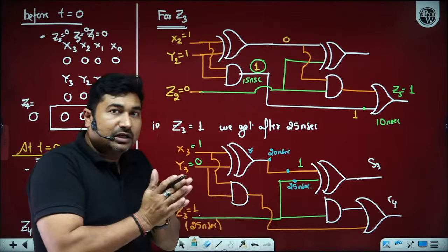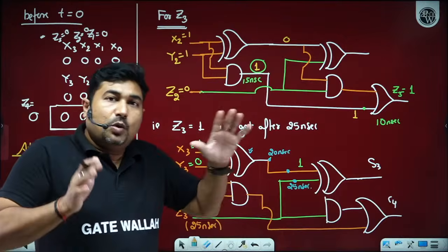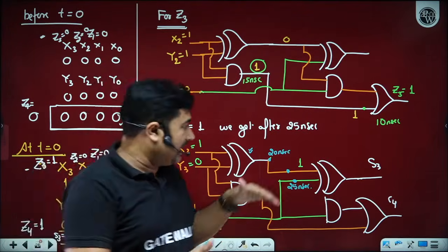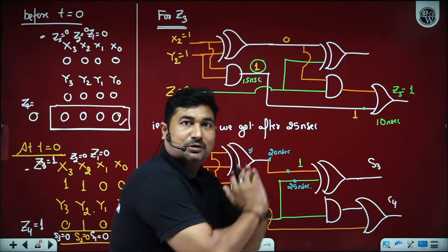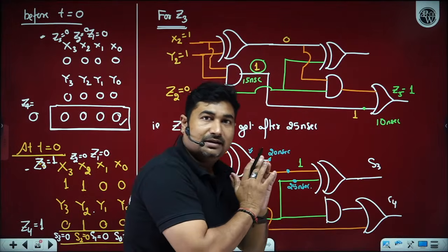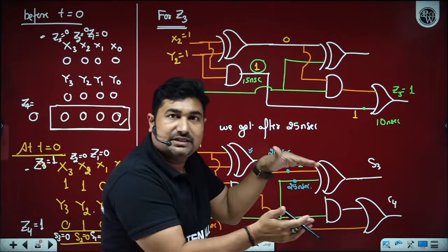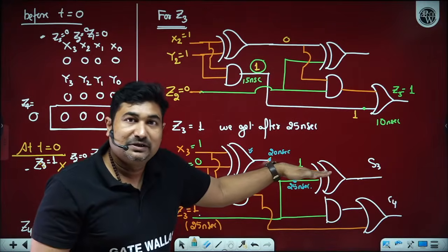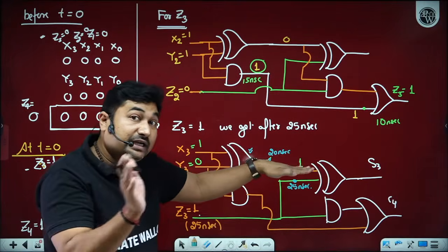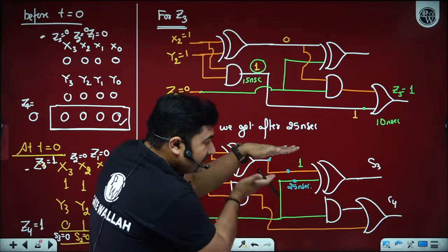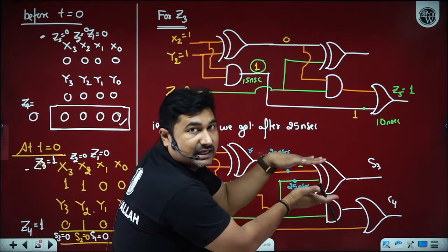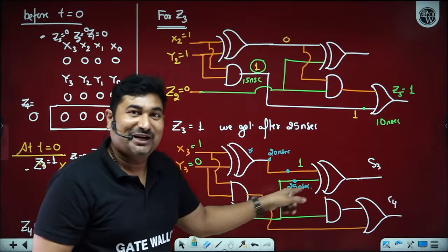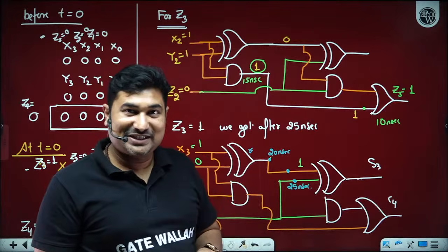Always remember, the logic gate output will be considered only when both the inputs are available. You can understand it like we have a train, and the train moves ahead only when all the passengers have reached. So this passenger reached after 20 nanoseconds, but we don't get the correct output until this other passenger also comes. That is coming after 25 nanoseconds. So let all of them get boarded to the input first. Is it okay? Yes, sir.